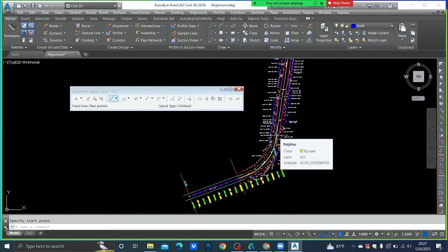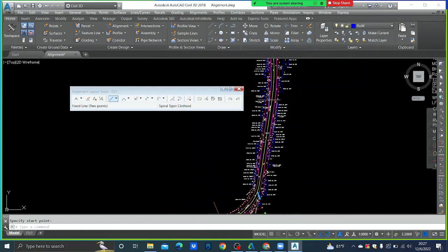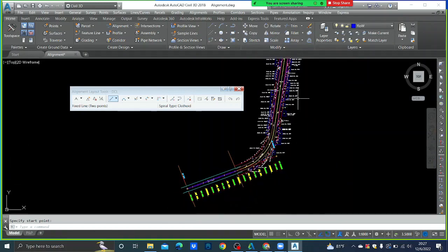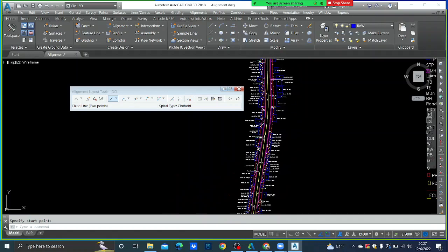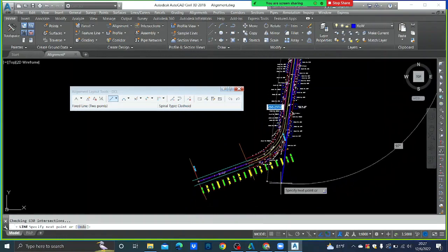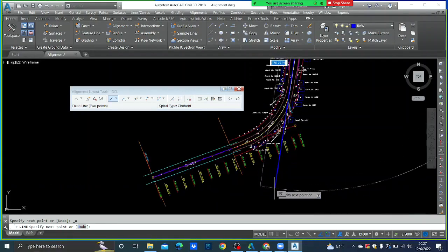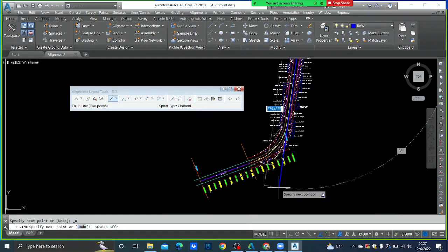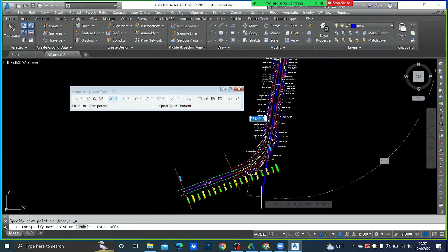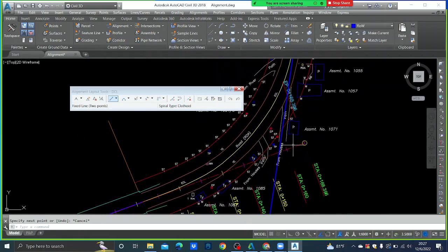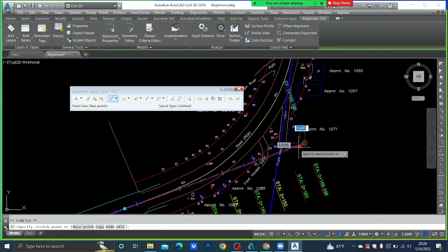So one thing that I propose is, before going for Civil 3D, you can draw a line connected from here to here and check how your line should come. So I'll draw a line like this here. Snap off, so you have to match with the existing line, right? So it is coming this way. So we'll take our alignment back to this point.